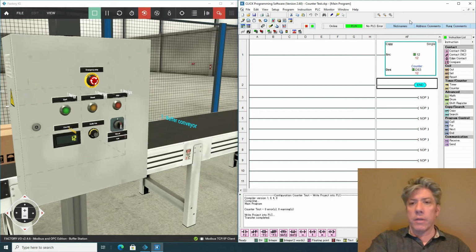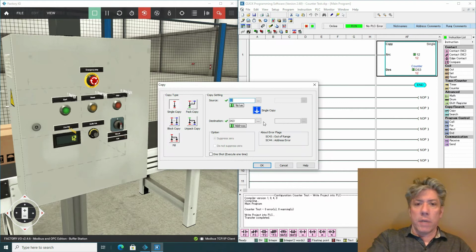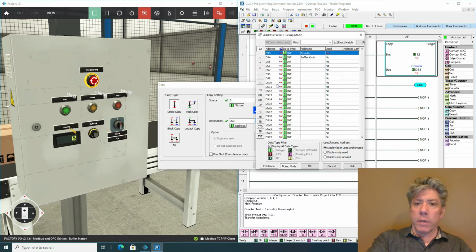Okay, so I can write out information in a continuous fashion, and if I really wanted to, I could turn on the conveyors with this. For example, I may as well, after all. Let's see. Instead of DS3, let's write out, the conveyors only go from, well, -10 to +10, and honestly I haven't figured out a way to give it a 10 number via the Modbus address yet, but that doesn't matter. I'm just going to put it at a speed of 5. I don't really want to control these conveyors in the backward direction anyway. And I'll just turn on the exit conveyor, for example.